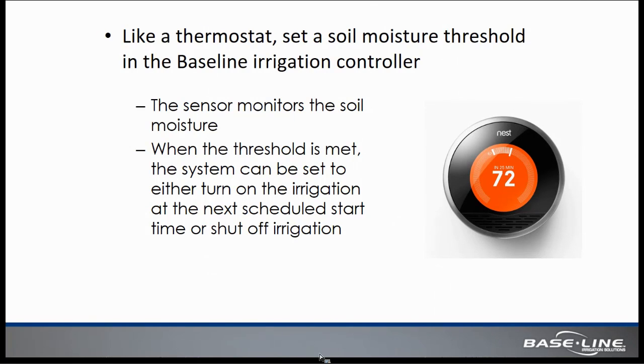And it again is taking into account the amount of evaporation that is occurring at any given time from that soil, as well as how much water is being used by the plant material during that same period. And we can use that information to maintain a desired threshold or level of moisture in that soil profile to meet our needs and or objectives.